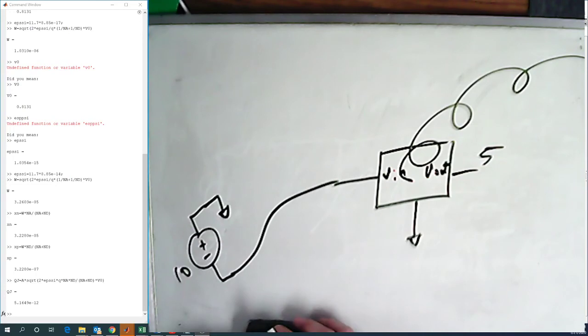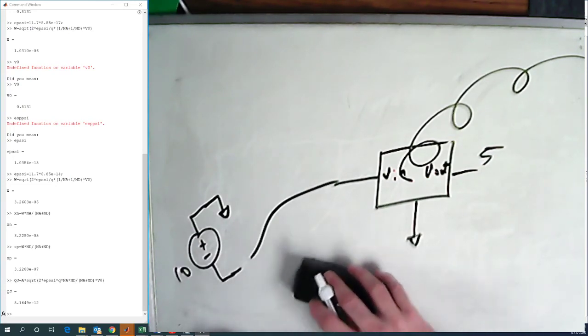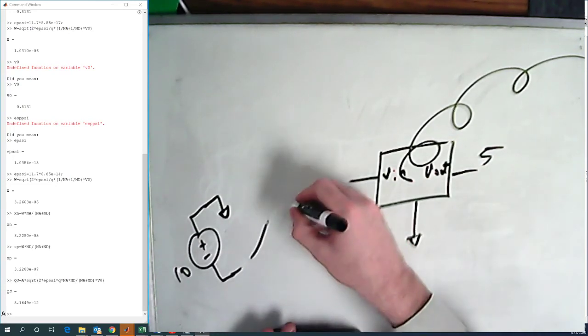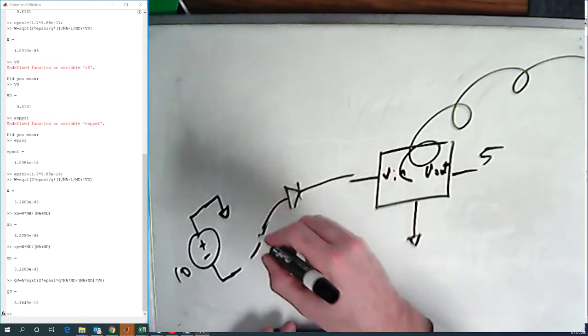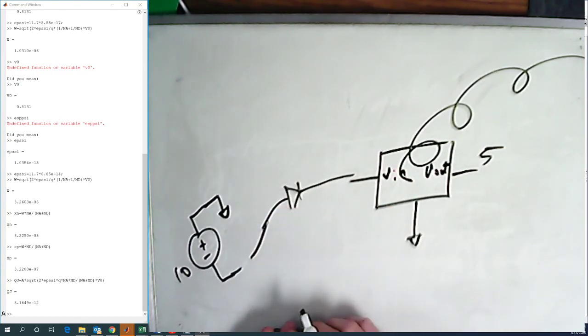And so what you can do with this, what I would do, and what I've done, is I just put a power diode in series. And now what happens is this is going to reverse bias. No current's going to go into this. No smoke is going to come out.